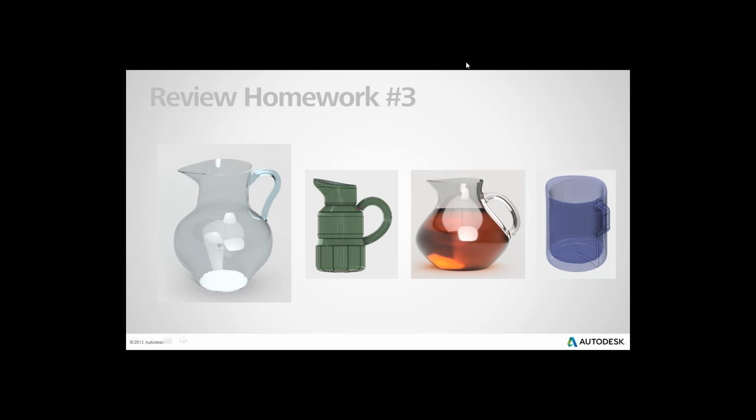The way I was thinking people might do it would be to make this sculpted shape of the body, slap a patch on the bottom of it with the patch environment, and use the thicken command to give it some sort of thickness, and then just draw a spline for the handle, and there's a command that's something like project, like path, construction plane along a path. And so you can click on it, and I think I showed it last week, where you can just guide it along the path, and then on that construction plane you can make your circle, draw your handle around, like sweep it around that path, and you're good to go. In 2 minutes you have your model done. But, you know, some people made it harder than that, which is good. This is a great learning experience.